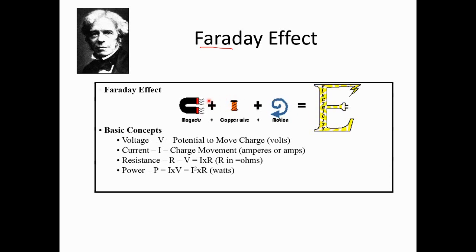By now I think you understand what's happening here. There is a constant magnetic field across the wire, and when you move the wire using mechanical motion, your conductor, your wire, sees a variation of flux as it moves. It sees dφ/dt. And we know that Faraday says if you have dφ/dt, then we create an electromotive force, EMF, which is a kind of voltage. So you create electricity. This Faraday effect represents the mode of generators.